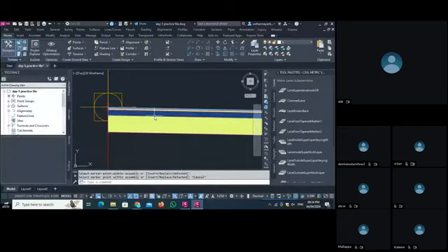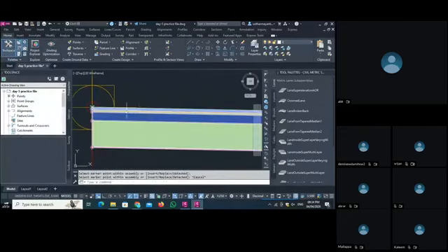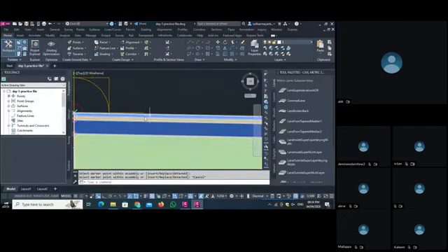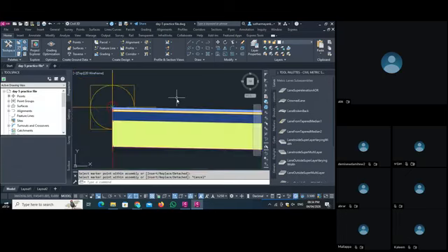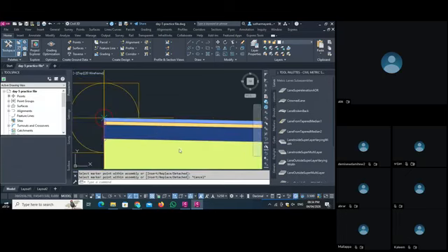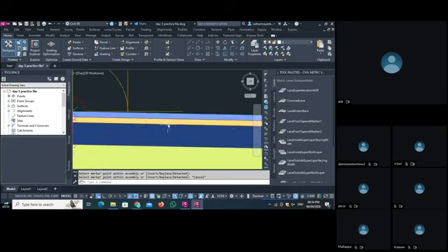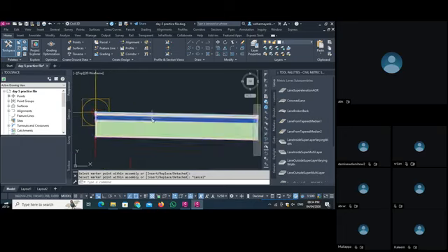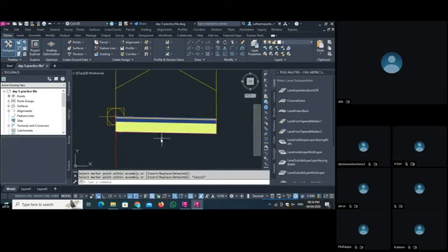Now see, we have all the layers here: the top layer, then the second layer, subgrade layer, base, sub base, all those layers are provided. But this is an auto sub assembly created by Civil 3D itself. If you use this, you can manage all your data with the help of the properties.